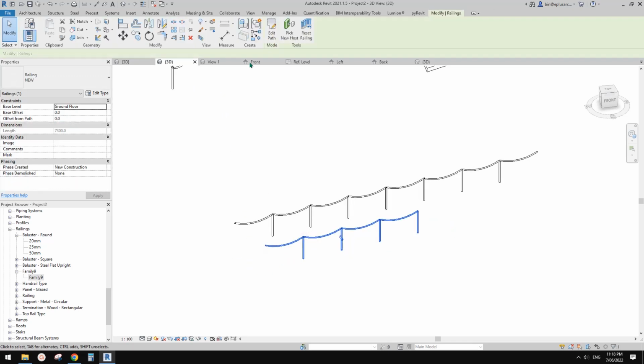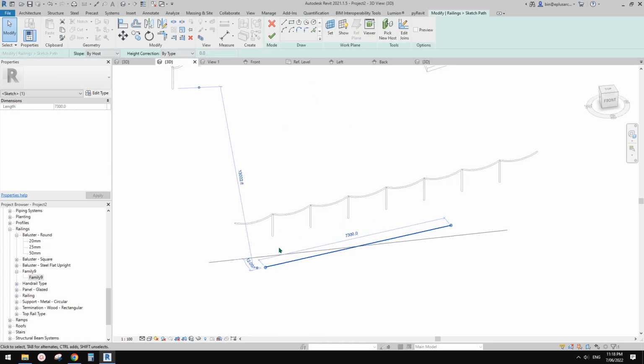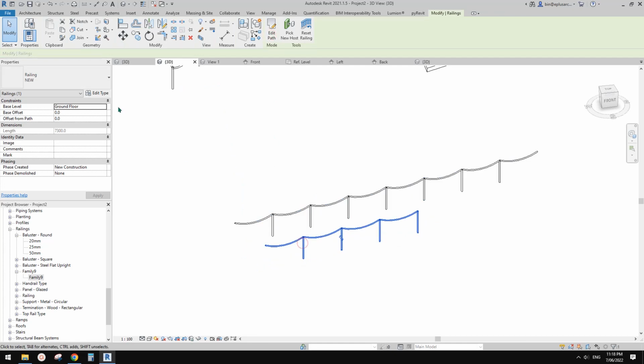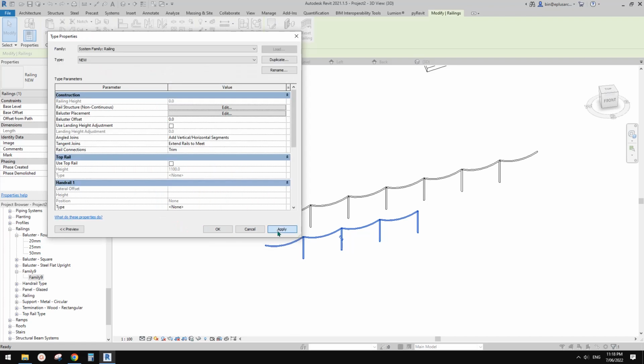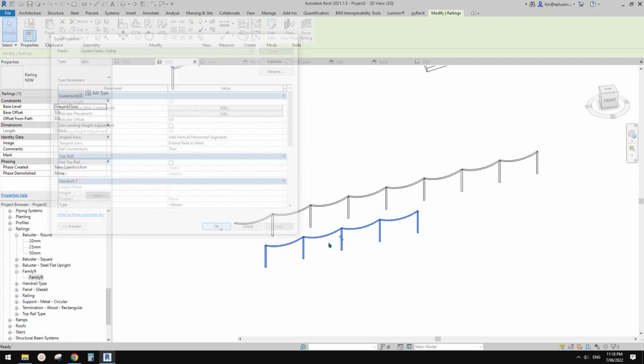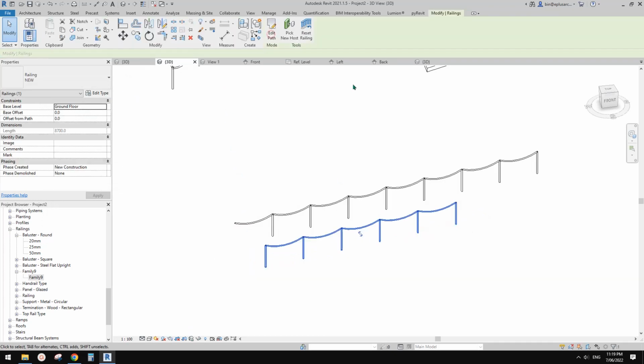It seems this railing is starting right at this point, which is good. But there's not. So this is probably the end, and this is the beginning. So we can add a start post here. This one, host top, we just use host by offset 900, and I think that should do. Yeah, good. I think this is probably it.